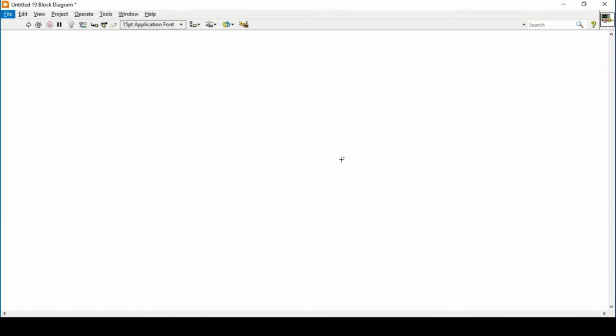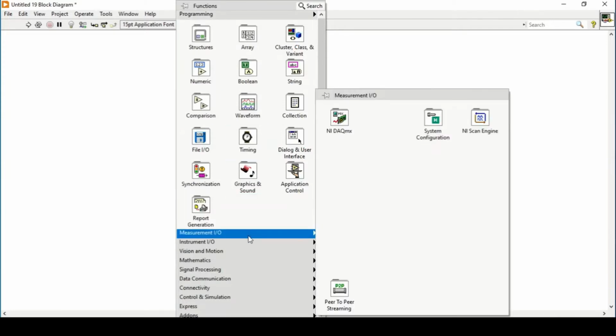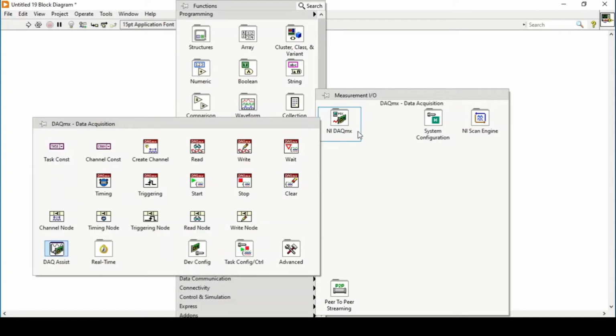After making connections with myDAQ and the IR sensor, as I have shown earlier, we will shift on to our LabVIEW program. Here I have opened a block diagram, and now we will start our programming, how we acquire some sensor data into LabVIEW. We right click on our block diagram, and there we have a measurement palette, and there we have a myDAQ device, with all of the blocks that are used for data acquisition by using myDAQ. These are simple functions that we can use individually, attaching them in a sequence to do the function that we want.